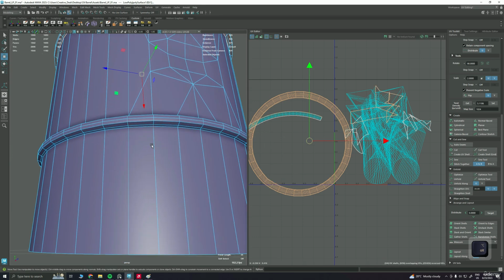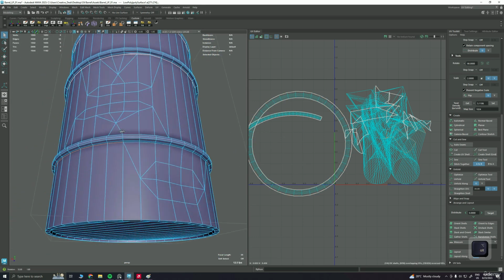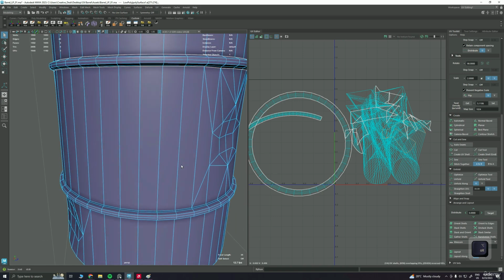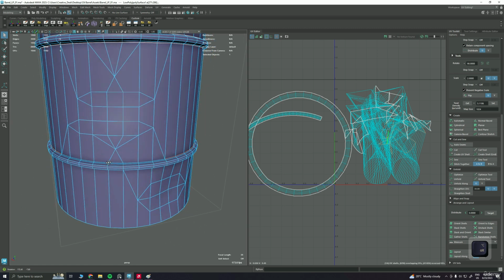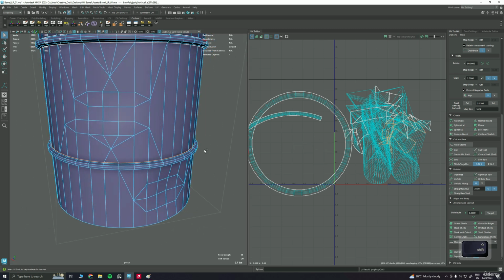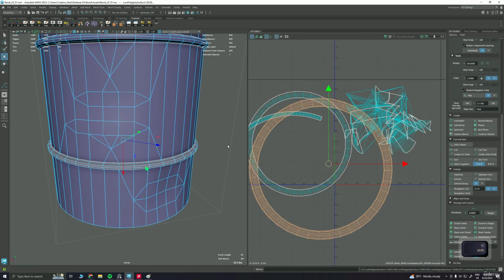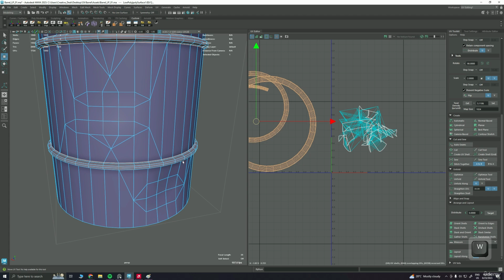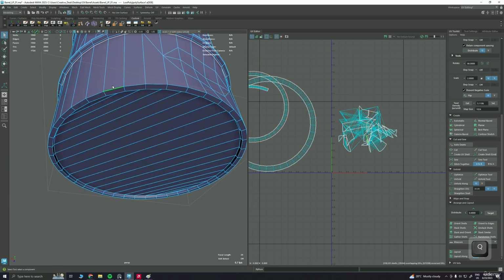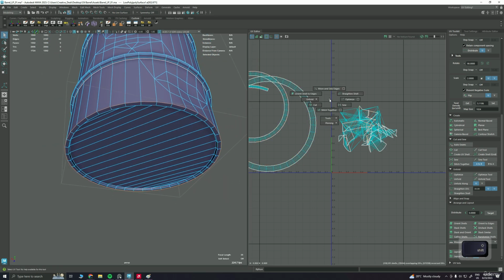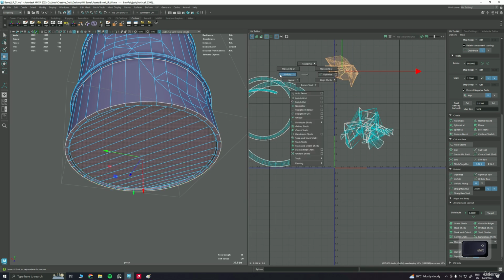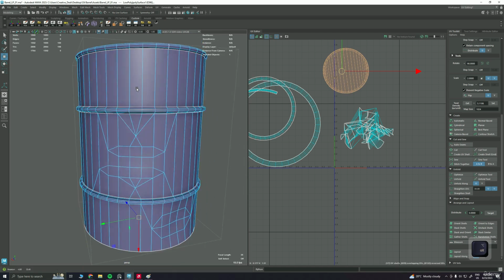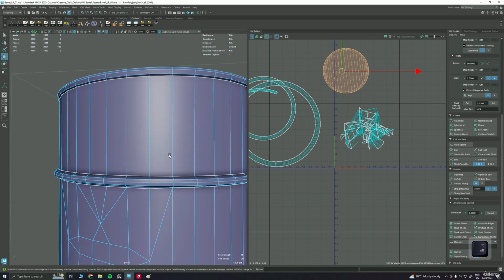Okay, so let's cut this over here. Make sure the edge is sloping all the way, and cut. So let's go on UV shell, select this and bring it out and unfold it. Okay, let's place this over here and let's cut this. So basically make a cut where there is a 90-degree angle. Okay, so let's cut this, and that's it.